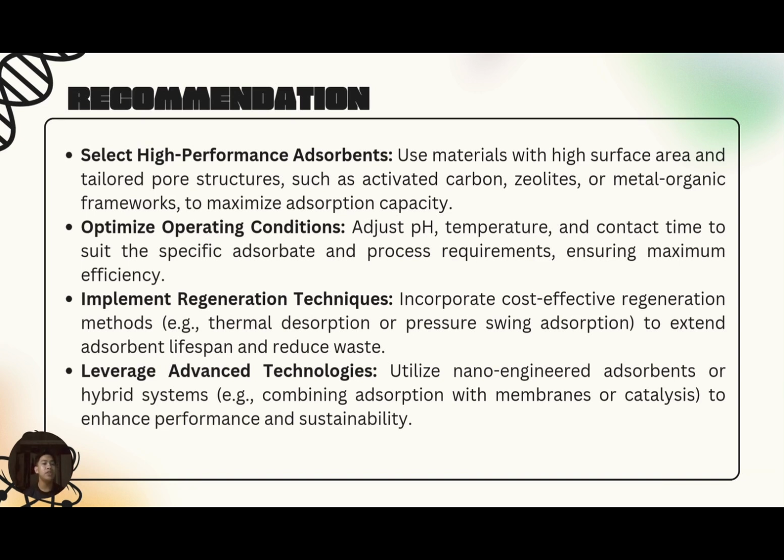To implement regeneration techniques, we can incorporate cost-effective regeneration methods like thermal regeneration or pressure swing adsorption to extend the adsorbent lifespan and reduce waste. The last one is to leverage advanced technologies. We use nano-engineered adsorbents or hybrid systems.